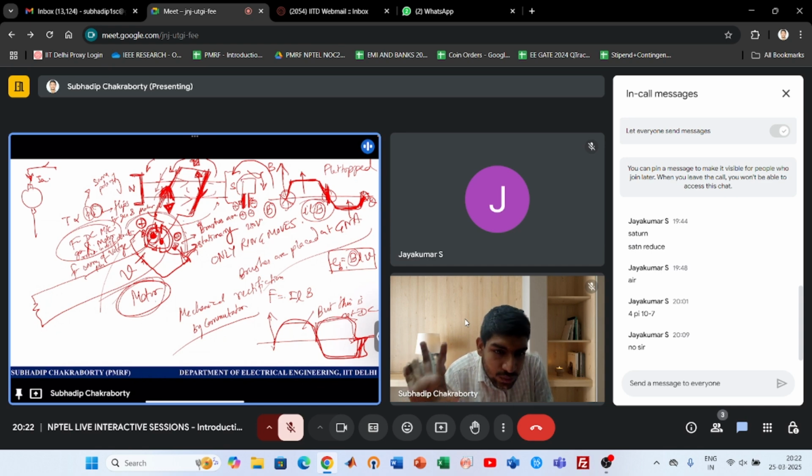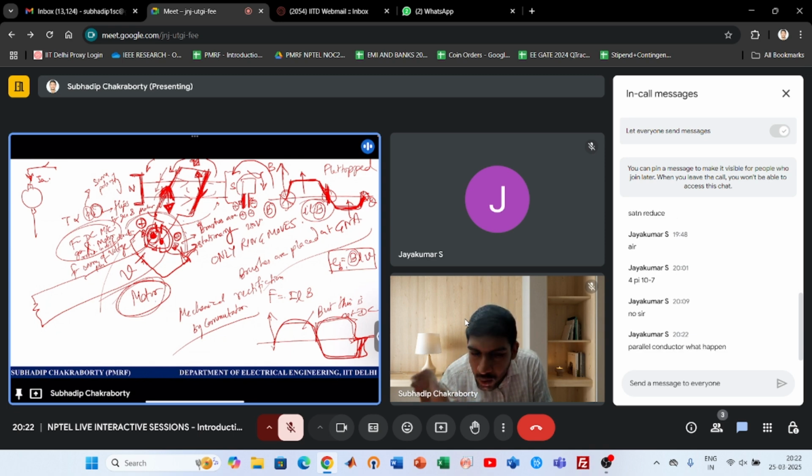So all the analysis we will do now is of the voltage and current that are tapped outside the brushes and outside the commutator. They are DC parameters. Is my point clear or not? Because inside the conductor, the current is not DC, because in a half cycle rotation, the current will flip its direction, right?